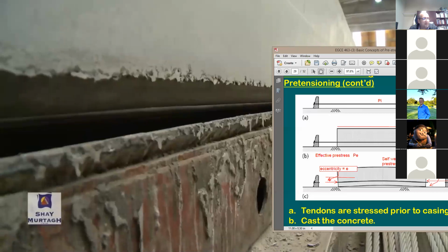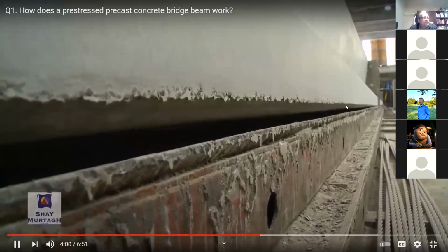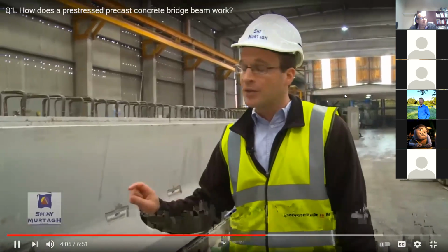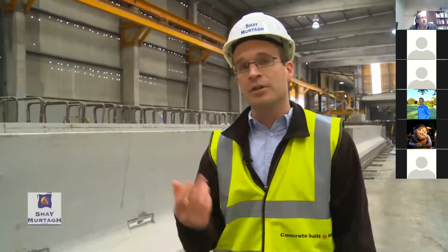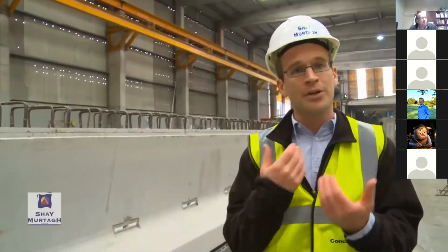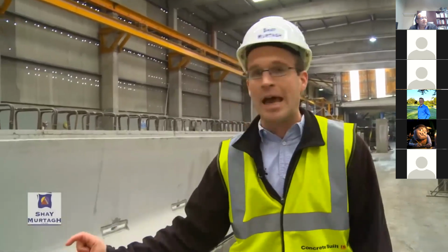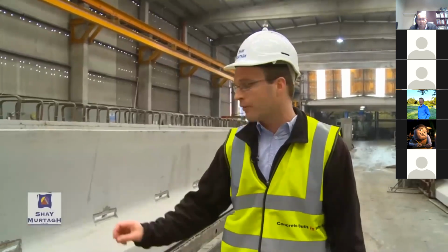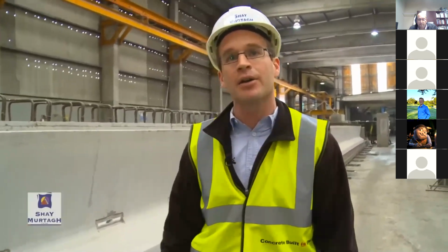The beam will actually lift up. You can see several millimeters across, 10 millimeters, whatever the case may be, depending upon the beam and the pre-stressing amount and layout used. It will actually camber up. Now, this is beneficial with regard to deflection checks as well. Generally, for bridge beam design, we don't need to carry out rigorous deflection checks, but from an aesthetic point of view, you don't want a beam visually sagging on site. So this natural camber that results from the pre-stressing operation itself will help eliminate the potential that that beam would be visibly sagging on site as well.